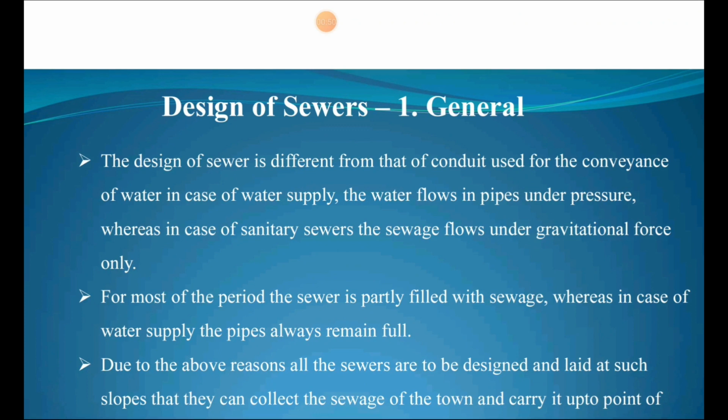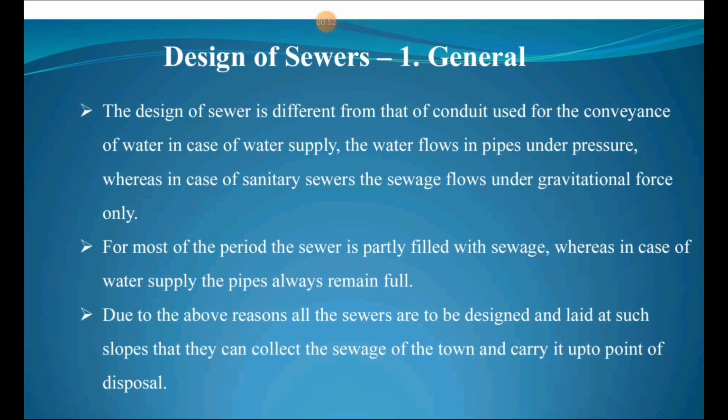First of all, we are going to discuss the design of sewers, and the design of a sewer is different from that of conduits used for conveyance of water in water supply. You must know that water flows in the pipes under pressure in a water supply system, whereas in sanitary sewers the sewage flows under gravitational force only. So this is the first major difference: water flows under pressure and sewage flows under gravitational force.